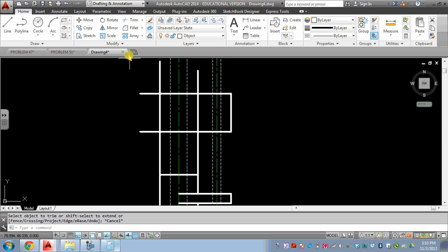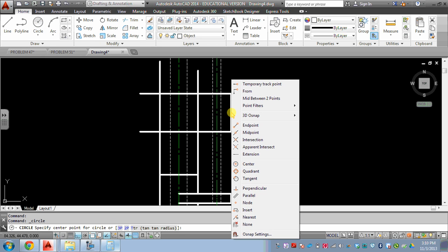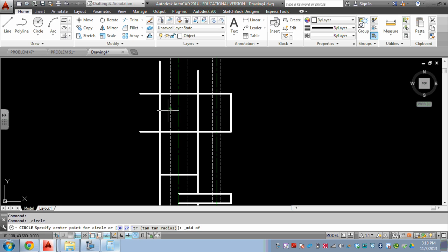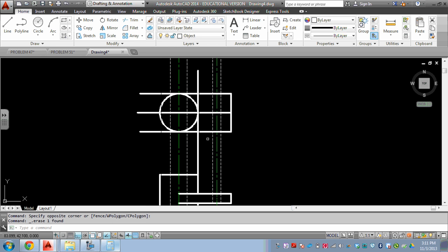Okay, looking pretty good. Now this one is where we can draw a circle. This one though is a little more difficult. I'm going to do snap override. We're going to need a center line anyway, so I'll select the midpoint here and bring it this way. So now we have that center line, I can actually use that intersection and come over this way. And right there is that circle. So we can take this now, erase it, hit delete. We can actually do the same thing with this, hit delete. It's starting to look more and more like it.